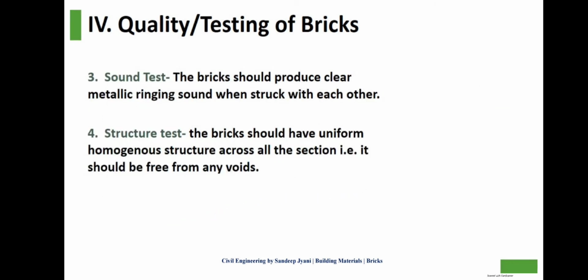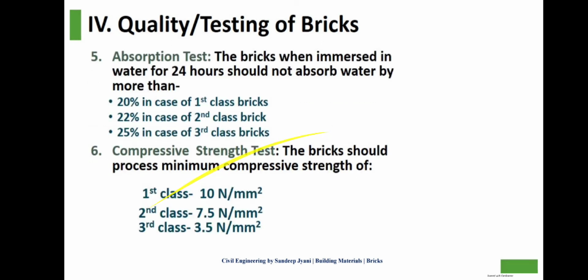Next, sound test. The brick should produce a clear metallic ringing sound when struck with each other. Structure test. The brick should have a uniform homogeneous structure across all the sections. It should be free from any voids.